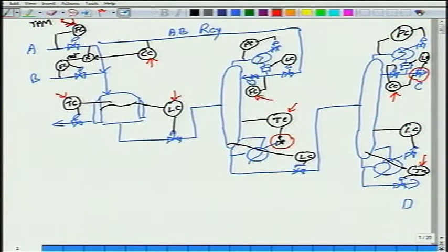When we had the throughput manipulator here, level control downstream was in the direction of process flow and level control upstream was in the reverse direction of process flow. Remember that? Okay. What was this called? This was called the radiation rule. You radiate outwards from the throughput manipulator.